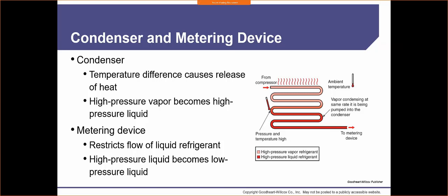All right? So we need that condenser fan motor running to be able to release the heat from the refrigerant, and by doing so, we're going to have that refrigerant go back to what it likes to be, that liquid state. Okay, and it's also staying in a liquid state because of the pressure. So we have that pressure-temperature relationship.